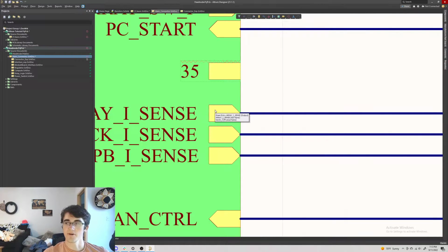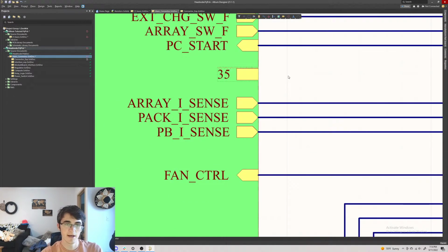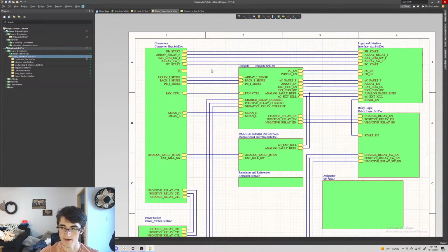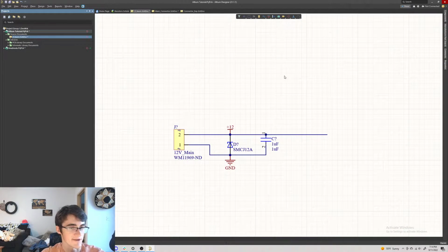But if we were actually using it and you defined it, it's a good way to check to make sure that it's actually understanding going from one end to the other. Because if it doesn't understand that, then you're going to have an issue connecting traces on your PCB, and things might not connect, and it won't tell you that they're not connected because the schematic doesn't expect it to. And so that's something really important to consider.